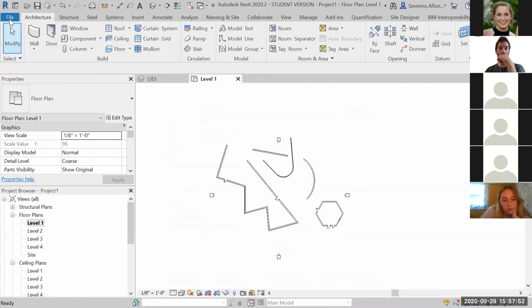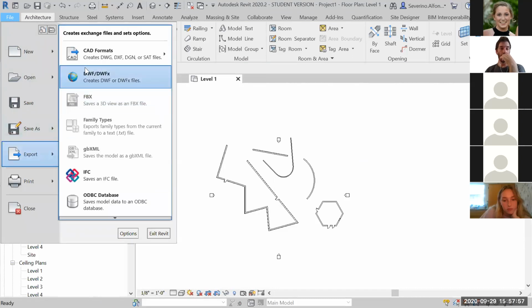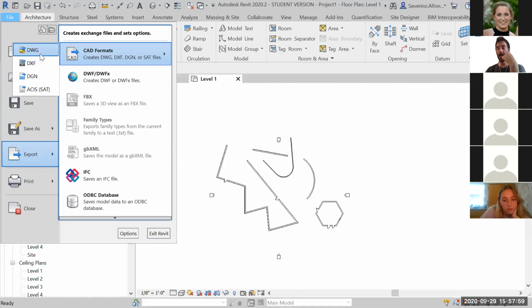Now, because we can export it as a DWG, again, export as DWG, that means that we can also take that into Illustrator directly. And because it comes with all of the layers, guess what? You can fix the line weight in a very easy way there if you want to be a bit more picky about those things. But there's a way to extract this thing from Revit.